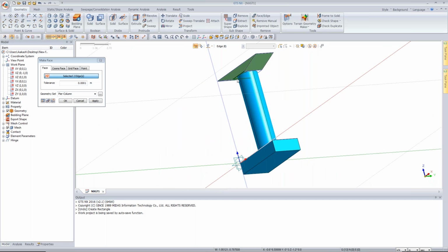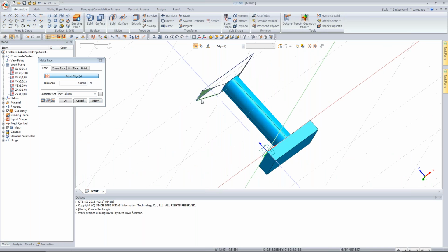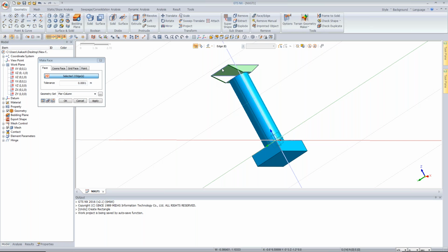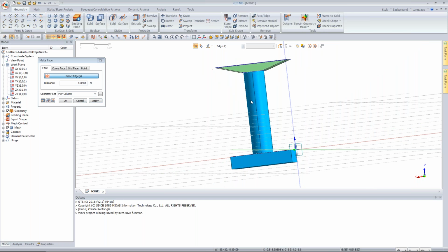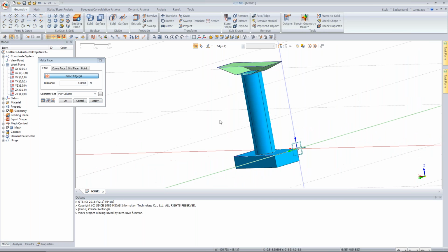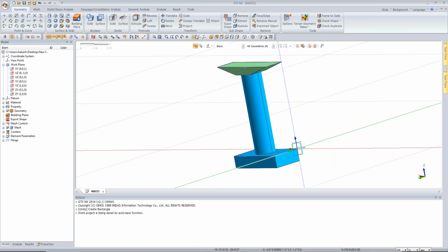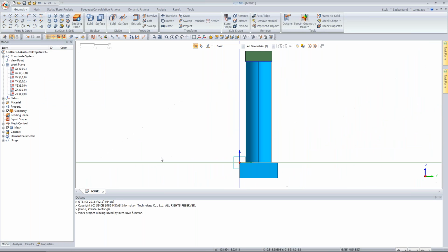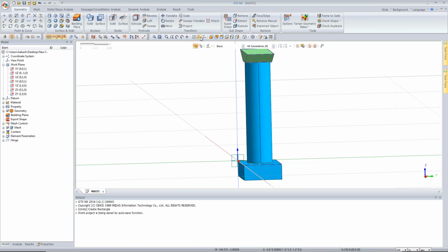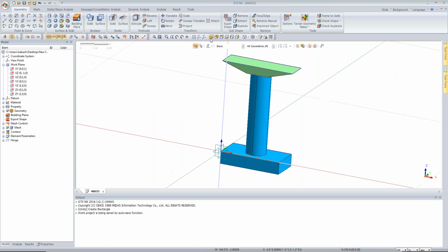Now the bottom 4, this part, and finally you have it. So for example, if you are bringing any DXF 3D wireframe into the program, you can use make face to create all the faces. Of course, remember that it should be an enclosed figure.